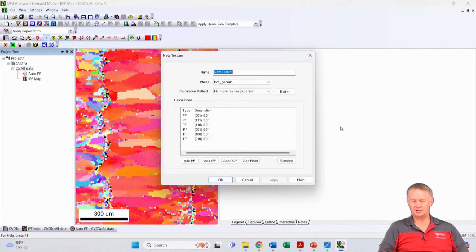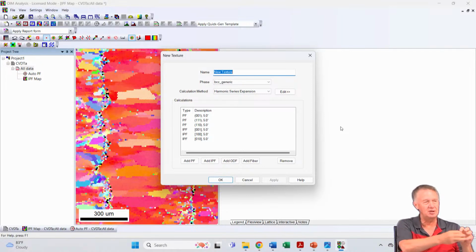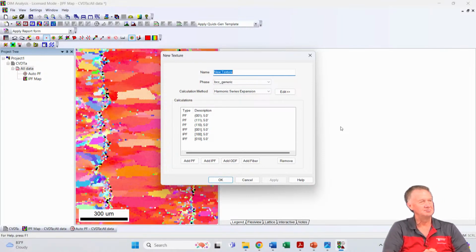Yes, a lot of times some of the old timers would say, here's a microstructure, and they show you a micrograph. And then they use descriptive material science, I would say, or descriptive metallurgy. Where they say, well, we have some flat pancake-shaped grains, and we have some elongated, we have some acicular structure, right? And they define the different regions. Here's some Chinese script precipitates in my titanium, whatever, right? So they use these terms that are non-quantitative, that are trying to be descriptive. But we try to move away from descriptive into quantitative. So that's a really good comment. Yeah, thanks.